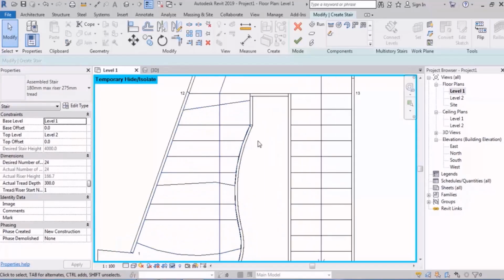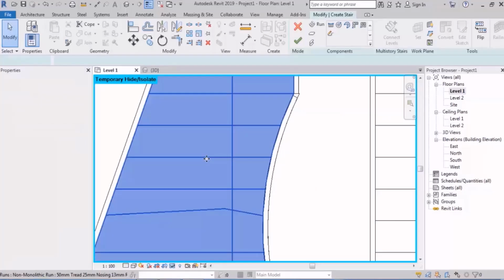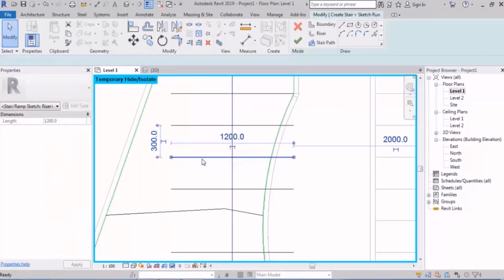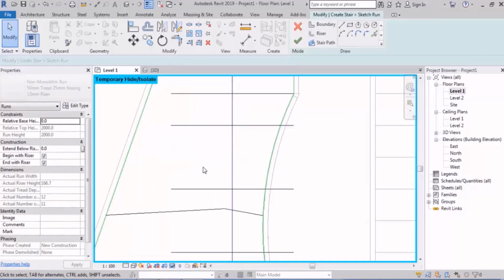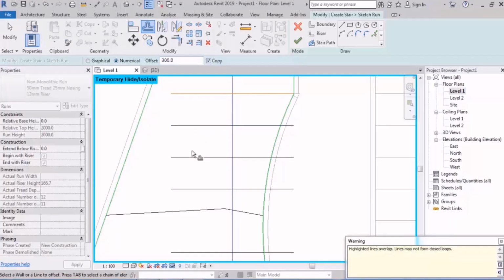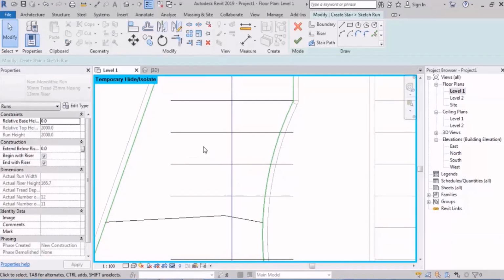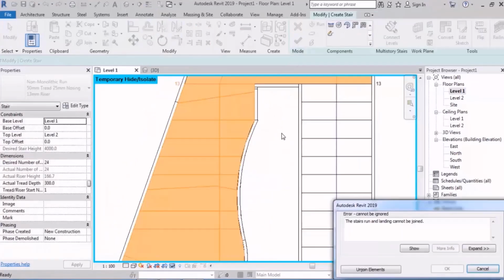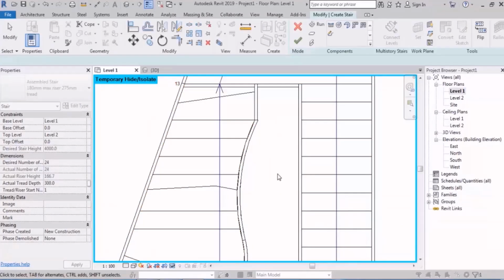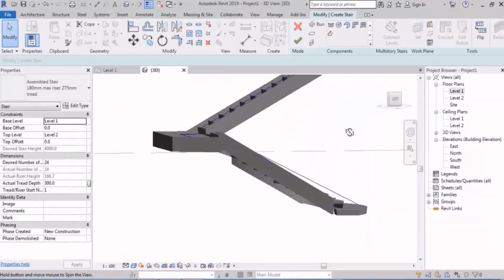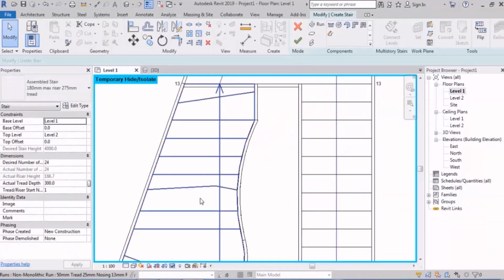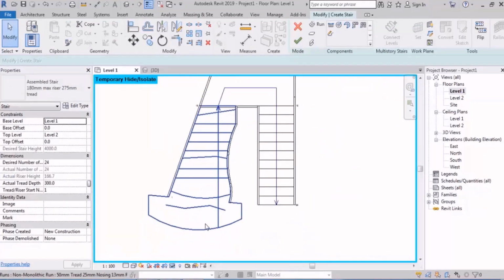One of the common mistakes is that, for example, someone deletes this and then he wants to offset. So he selects the offset and enters, for example, 30 centimeters. And when he offsets, there will be 2 there without him understanding. And then when he clicks on finish, this message will show up. So when we go to 3D, we see there's a conflict. And when you go back and, I don't know, count the lines, you see everything is alright.